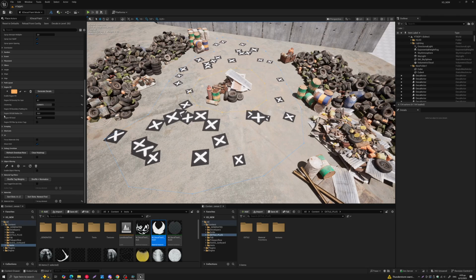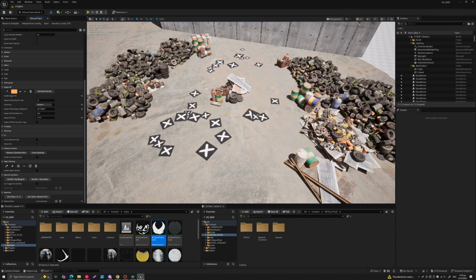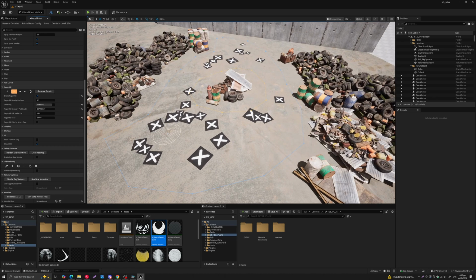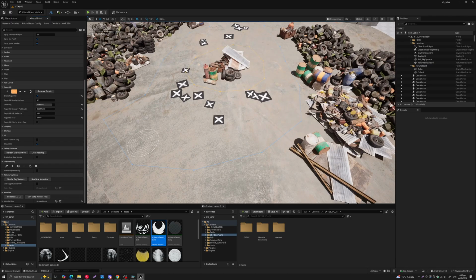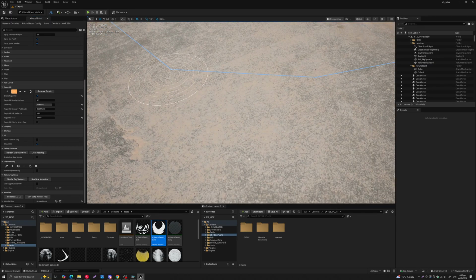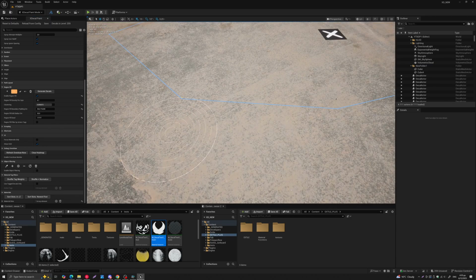So basically, you have the region fill boundary padding. What this does, I'm going to turn this up to this big number here. So this is about 200 centimeters. When I click on that, what happens is that the decals now try to avoid the edges of the main region, so the blue line. You can increase it even further, and those decals try to come to the center. So this is another way to control how those decals are placed within that region. The region fill edit radius, here if I come close, you'll see that I need to hover over a point to be able to drag it.